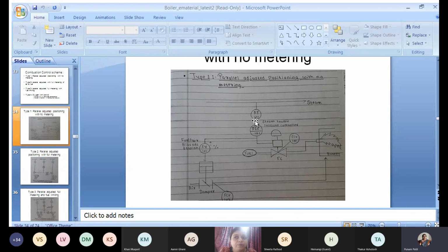ओपन होने के लिए कंट्रोलर का सिग्नल, ये जो आउटपुट सिग्नल है, it must be high, राइट? लेकिन इसको PT तो इनपुट लो दे रहा है, but controller output we are expecting high. PT क्या कर रहा है? If the demand is more, steam line pressure is less, that it is measuring and giving the signal to controller, but controller का आउटपुट must be high. So for less input, controller must give high output. So what you will call, controller कैसा होना चाहिए आपका डिजाइनिंग में? रिवर्स एक्शन. Reverse acting, correct. So in the designing, you have to select reverse acting controller.